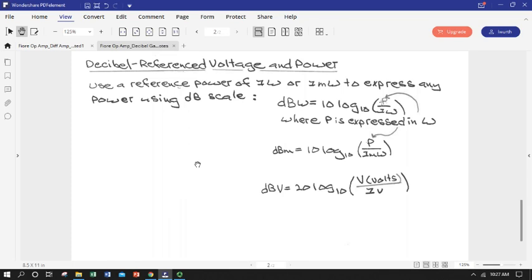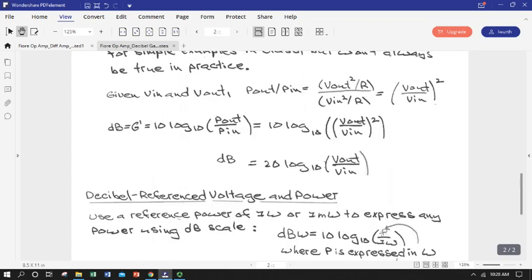They're kind of logarithm happy, I guess. So this is something that you will see in practice in the study of electronics, especially any time that there's a lot of amplification needed for something. So if we can express a voltage ratio on the decibel scale using this equation, we could also express a single voltage using the same equation and just use some denominator that's a known reference.